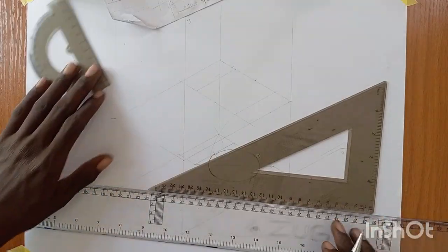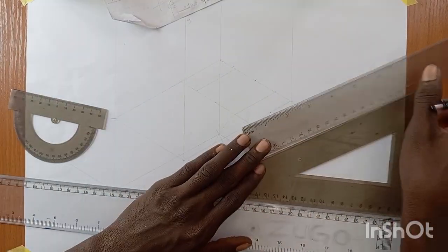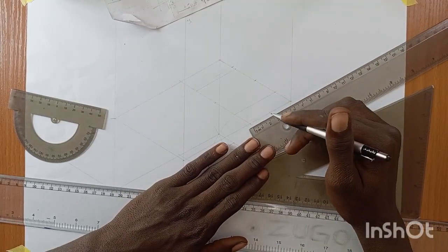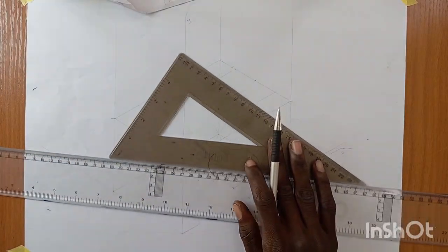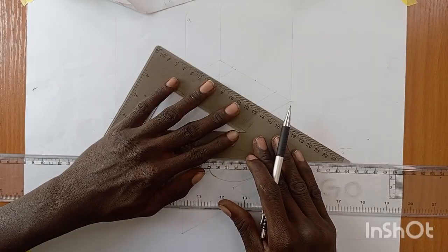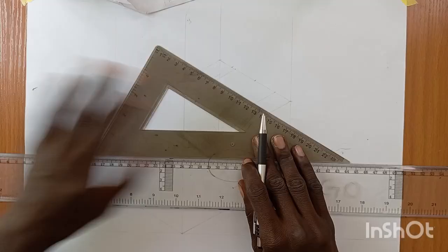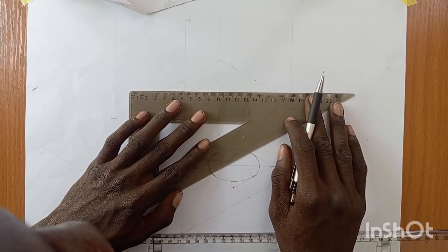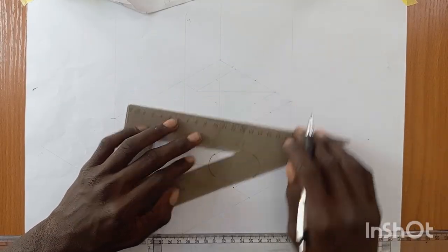So now, we're going to divide this into 2 also. We measure 25 from one side and cut it. So now here, 25 here. Okay, I've already cut it in the beginning. So now I can use my 30, 60 set square to bisect the line. You see that our interested line is not this one, but this one. So I'm going to cut this one, also cut this. Now the next thing is to draw a line that passes through diagonal, like this. So now I will bisect it here.